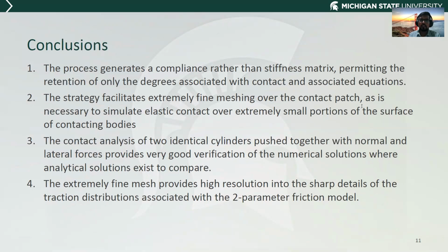And another one is the contact analysis of two identical cylinders, which is shown here, showed a good verification of the numerical solution where the analytical solution also exists, and it shows a very good comparison between them. Also, the extremely fine mesh provides a high resolution and the sharp details of the traction distribution associated with the two parameter friction model.